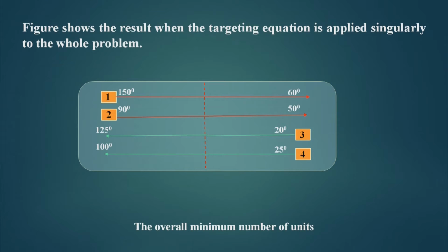But if we pass heat through the pinch, this will be a single problem, and here the streams will not be counted twice. If I apply the units target here, there are 4 process streams and 2 utility streams, which makes it 6, and U minimum is 6 minus 1, equal to 5.